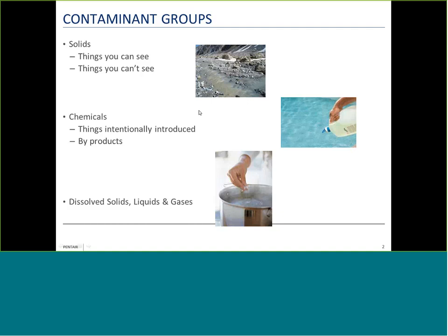And solid contaminants. We measure solid contaminants by the general name of turbidity, the overall number of floating particles in the water stream. This can be dirt and sediment, colloidal particles such as silica or ferric iron, bits of wood pulp, anything that can be found in nature that can be ground up small enough to essentially float in water.